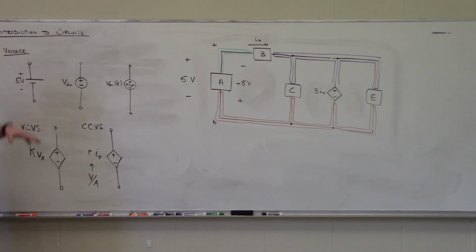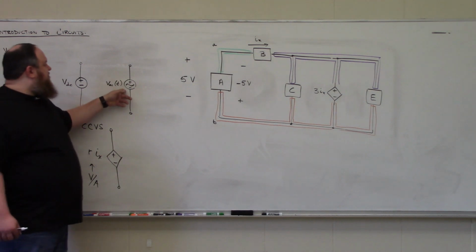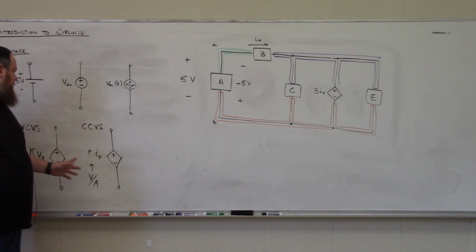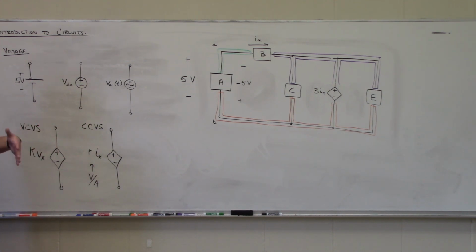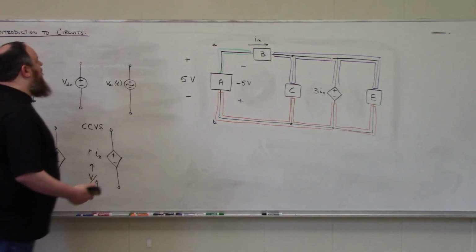All right, so these are the 5 different types of voltage sources that we'll see in our circuits. This one is specifically a DC voltage source. This one is specifically an AC voltage source. Our dependent sources can be either AC or DC. You usually won't see a squiggle even if it is an AC quantity. It's going to take students a bit to get used to these dependent voltage sources, but I promise if you just think about what's going on instead of being intimidated by them, it's actually pretty easy to utilize them inside your circuits and figure out what's going on using circuit analysis techniques. All right, let's move along to current now.